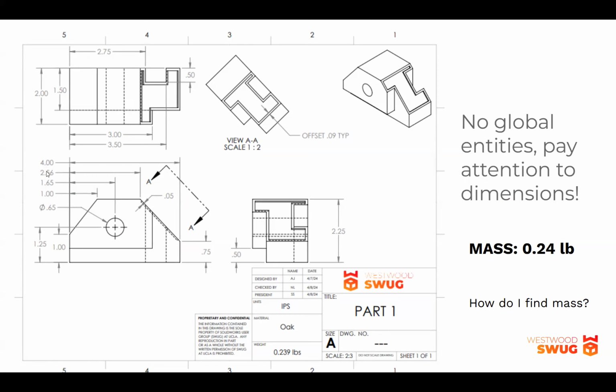A 4, for example, is the length of this piece. And if you look at this symbol, the circle with the slash, that is the diameter. If it's not a full circle, you'll get a semicircle, and it'll be different with an R. That's not important right now because we don't have something that says it, but just for future reference.